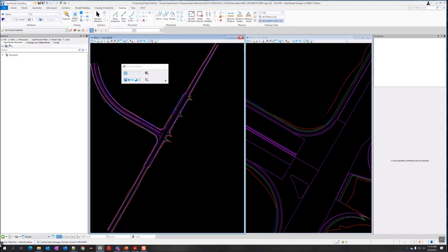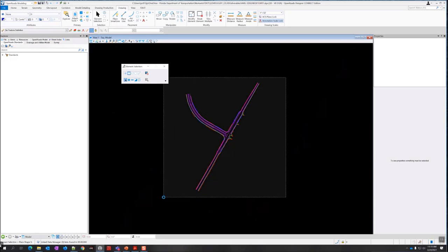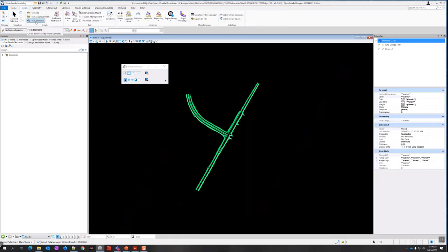All right, so we're in the DGN file, and now we can create. I'm going to switch down to just the one view. So we need to create a selection set of all the elements so we can create the surface here. So I'm selecting everything. I go to the terrain tab, create from elements. Feature type should be break line. It's very similar to what we did before. Feature definition is a DTM proposed. I don't think we have one for just the top and bottom, so it's just a DTM proposed.